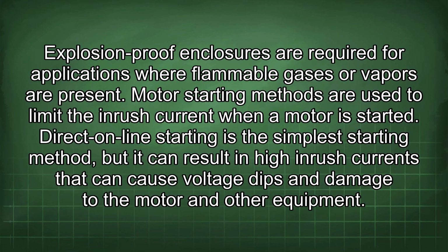Motor starting methods are used to limit the inrush current when a motor is started. Direct online starting is the simplest starting method, but it can result in high inrush currents that can cause voltage dips and damage to the motor and other equipment.